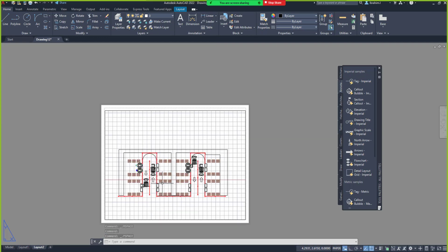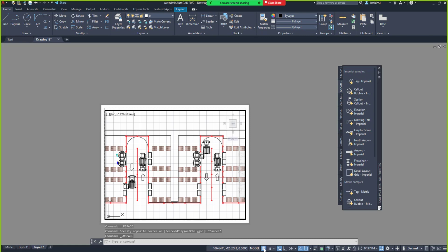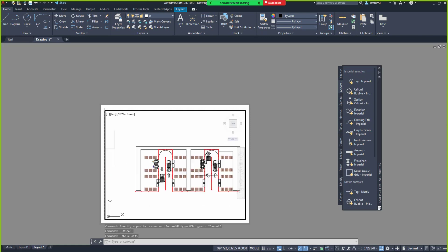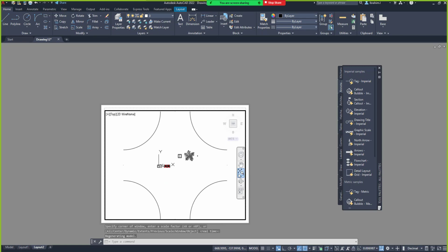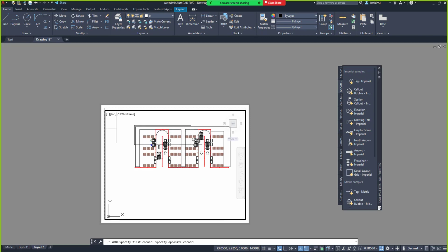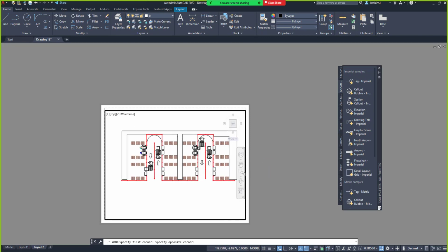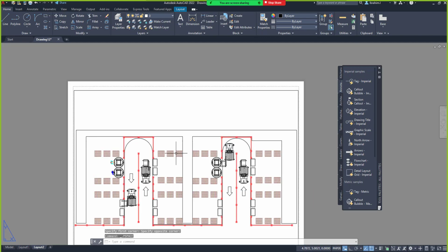If I want to see my design clearly, what do I need to do? All I need to do is double click into my design. While I'm able to zoom in inside the model workspace, I go to my grid. Can you see my grid here? This is my status bar here. I click on this icon, and then I'm not seeing that grid anymore. So I can place my design the best way that I want it. Go to my zoom window, adjust my view, make sure my object is being captured on the workspace, and then after that I click outside. Right.